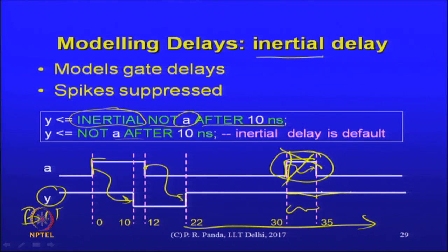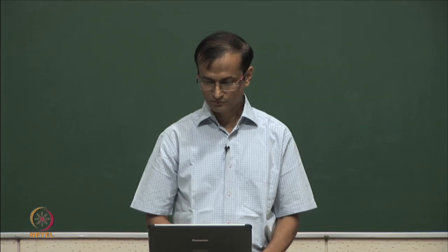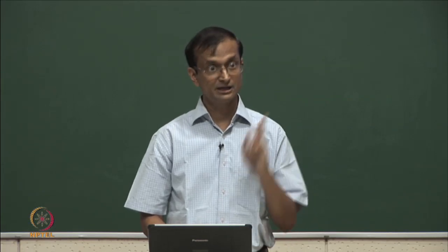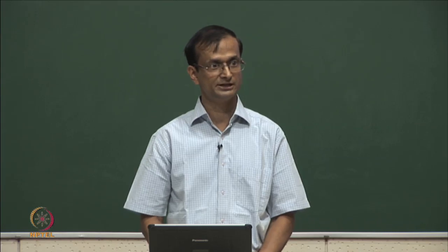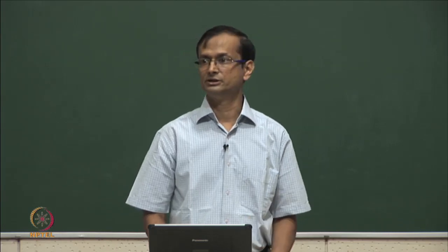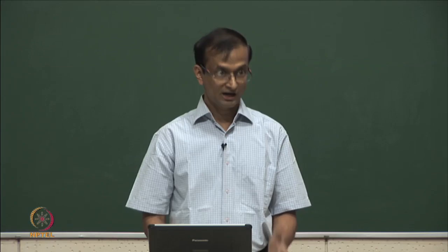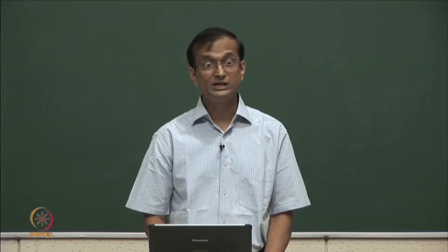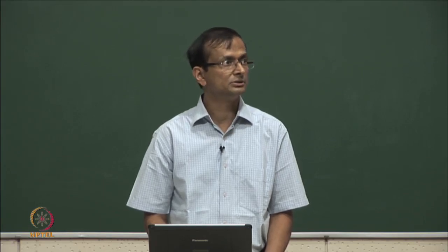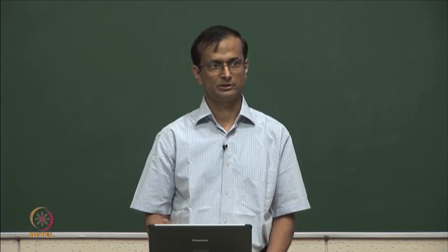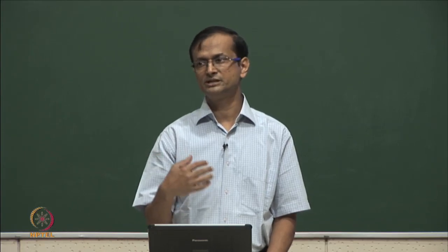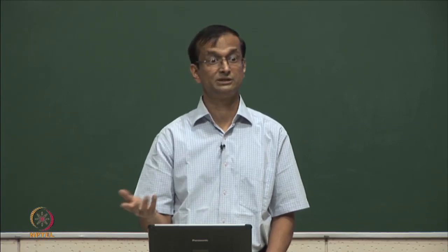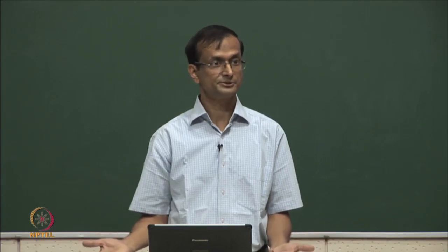So, is there any default value for this delay? Default value is 0. If I did not specify, like in the earlier statements where I did not specify a delay, then you are saying that the output should take the new value after 0 time. But how it is coordinated is something that we will get to, but if you do not specify, then it is a 0 delay specification. There is use of a 0 delay specification also. The use is that if it is submitted to a synthesis tool, right, you specify the functionality, you submit that functionality to the synthesis tool and you tell the tool, you give me the best circuit.